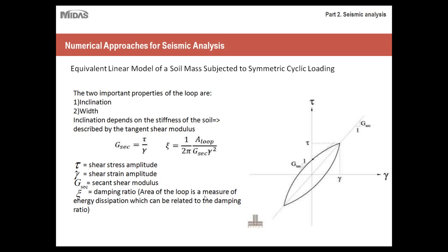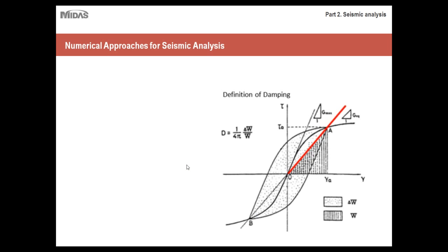So I'll go into more detail about damping ratios, but just keep in mind that the damping ratio, the parameter that you input for your seismic loading, or for the soil parameters for your seismic loading, is directly related to a model such as this. So before I move forward, let's talk a little bit about damping ratios and why that's important.